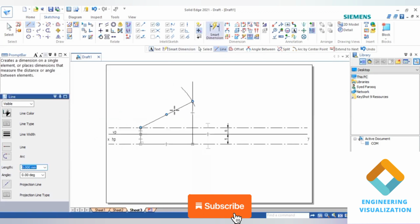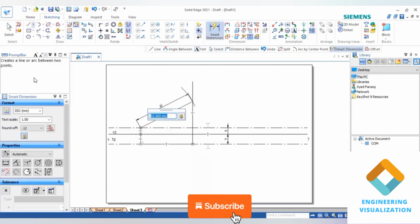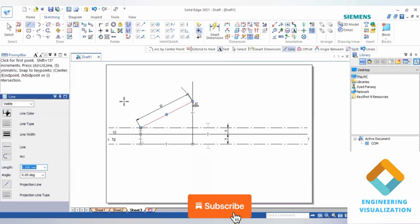Okay, now at this end point of the line we can draw the locus line. So we can measure the length. It is 85, that is true length. So here at this end point you can draw the locus line.